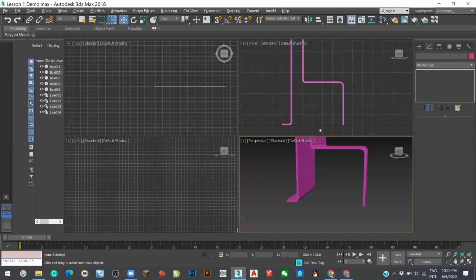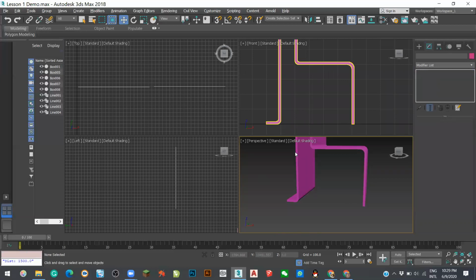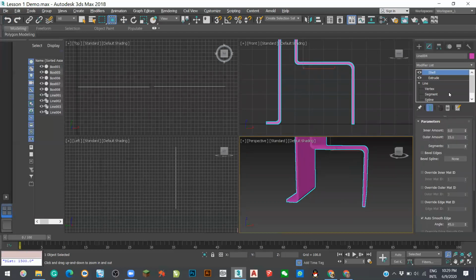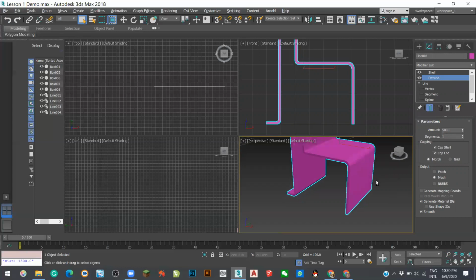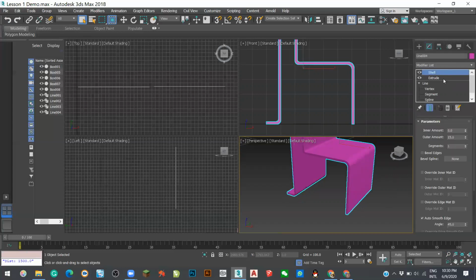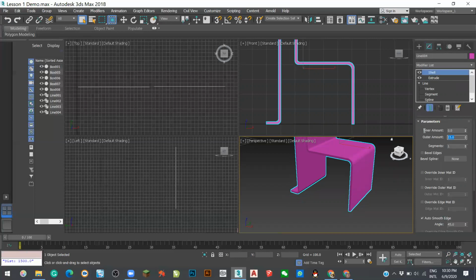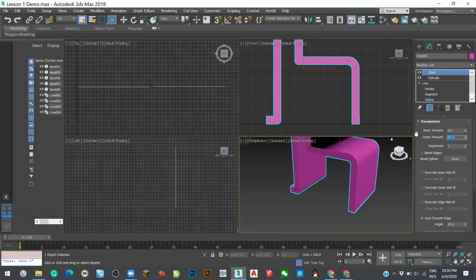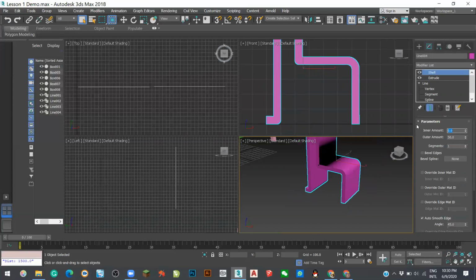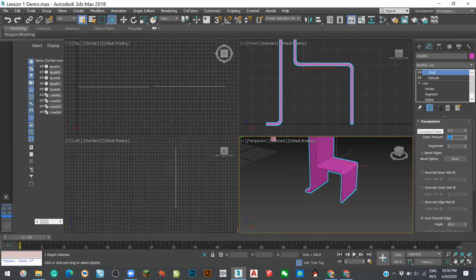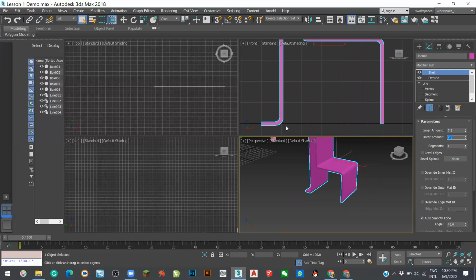I will check whether it is the same. Yeah, it's the same level. Okay. If I'm not using, I undo. I just select this object. If I want to change this extrude, I go under the modify list extrude, and I can change to 450. And if you want to change the shell, you also can, for example, 50. Or you can change inner, like 7.5, then outer will be 7.5, something like that.